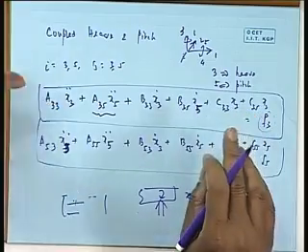So what is happening is that we are adding now a coupling, that although the ship is heaving and pitching together, supposing it is heaving and pitching at the same time, what is my force in the z direction? There will be force coming because of heave, but there can be force in z direction because of pitch also. This is what is called coupling. Therefore, you cannot solve heave by itself. You have to solve heave and pitch together, because heave is influencing pitch, pitch is influencing heave. This is what is called coupled motion.